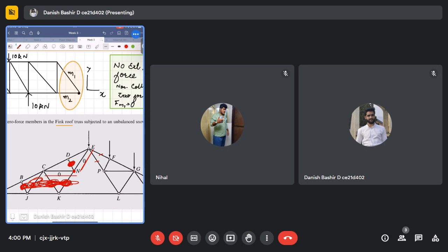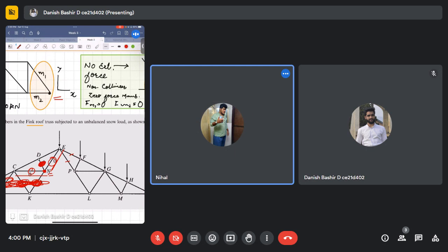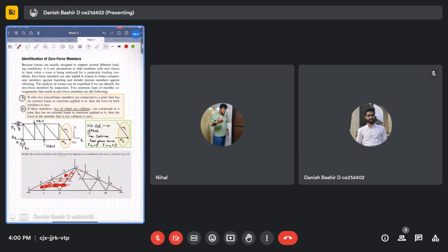NE member and CN member, carefully. Take joint N and consider this example. If at any joint there is no reaction force and no external load, at joint N both are satisfied. NE will be zero and CN will be zero. You got my point? Yes, sir. It's clear now. Yeah, it's like this. You have to come from this side, and this side.